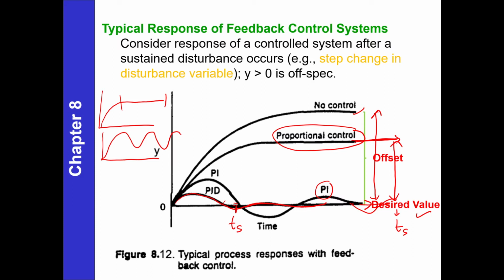When we introduce integral, it will eliminate the error, but it takes some time to get to steady state. As compared to that, derivative mode will reduce the error and bring the response back to the set point faster.